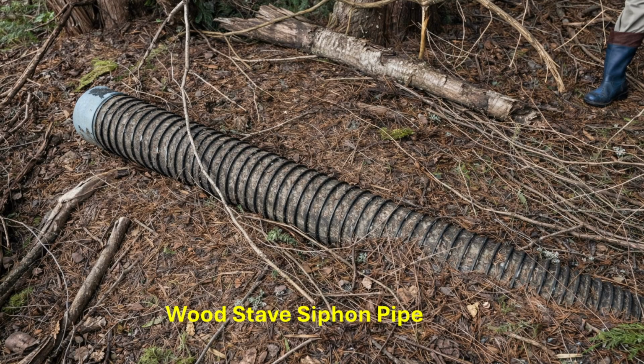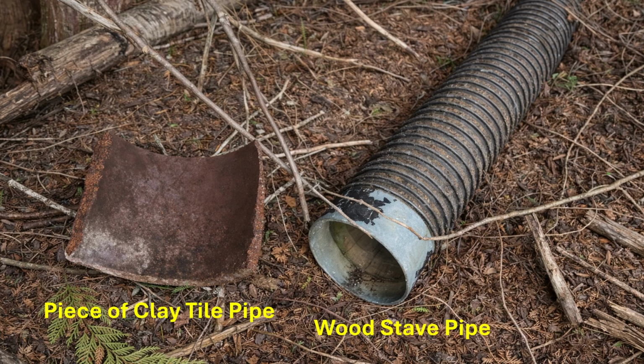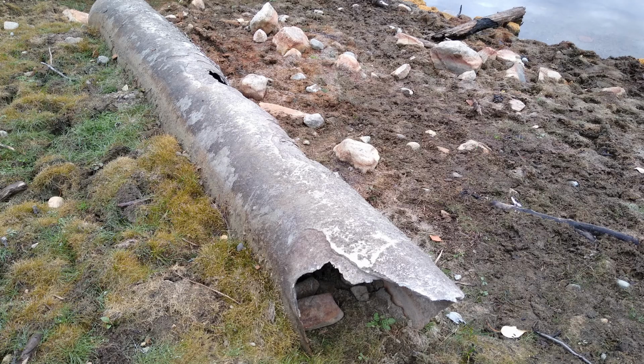The original siphon pipes were made using beveled strips of wood we call staves, and these were bound tightly together with steel wire. Pipes were commonly made using wood staves or clay tiles before plastic was invented. In 1953, the wood stave pipe was replaced with the current 880-meter-long, 400-millimeter diameter transite pipe, which was made using asbestos and cement.